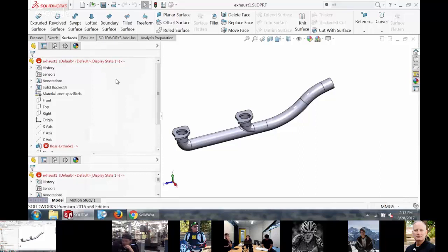The reason is that if you've got a part that's released and then there's a part that's got an external reference to it that's not released, they're out of sync. You actually have to take that one that's been released out of release and check them both in at the same time. So you end up revving stuff for no real reason than the fact that it's got an external reference. So it can get pretty ugly.